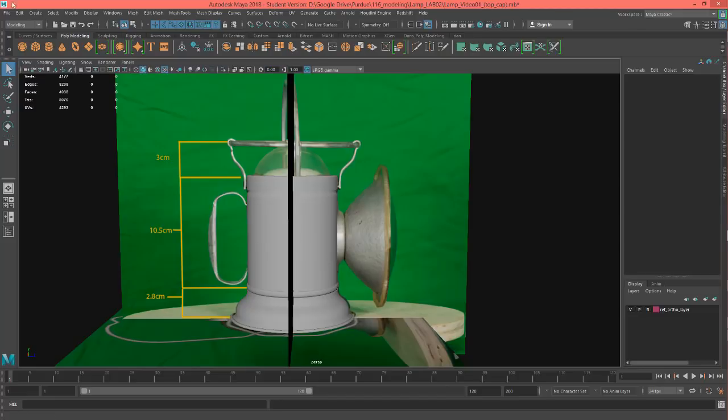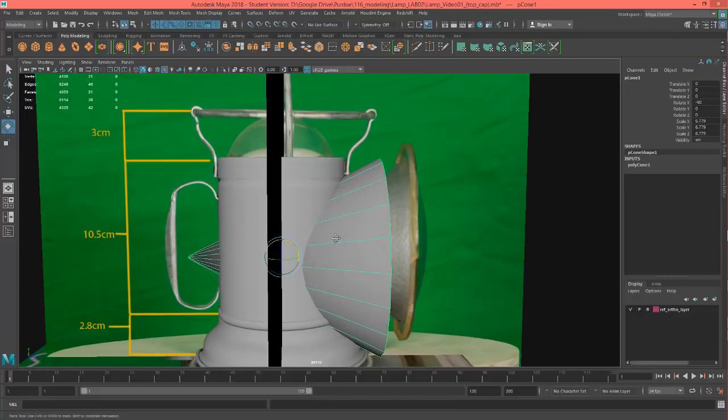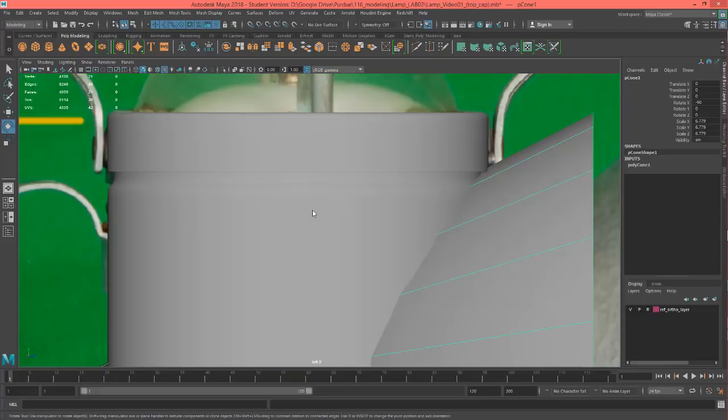next to it. Okay, so let's go ahead and just make a cone here, and I'm just going to scale this up until we see it, and then we'll rotate it. Holding J on the keyboard, we'll snap it into increments. Let's go into our left view.